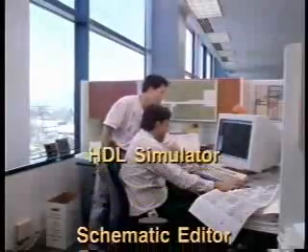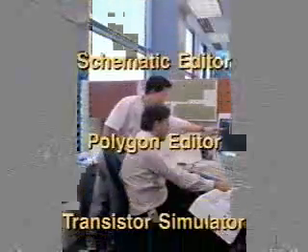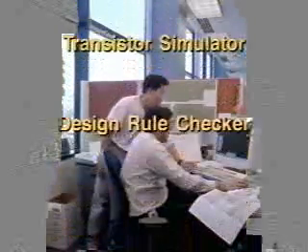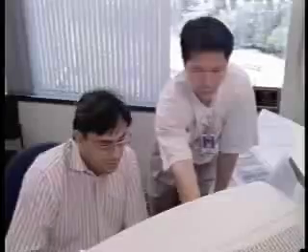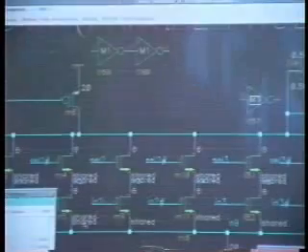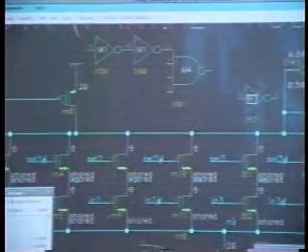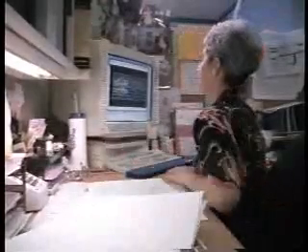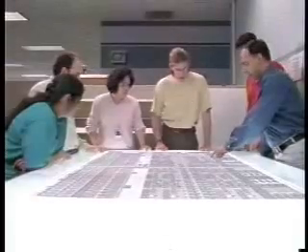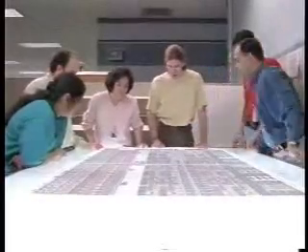Designing these circuits requires software and hardware tools like computer-aided design and computer-aided engineering. After circuit designers complete each block of circuitry, the computer checks for accuracy based on geometrical and electrical design rules. A mask designer takes the circuit schematic and manually lays out the channels in each layer of the mask and generates a master blueprint. These drawings are usually 400 or 500 times the actual size of the chip and enable engineers to visually check for errors.